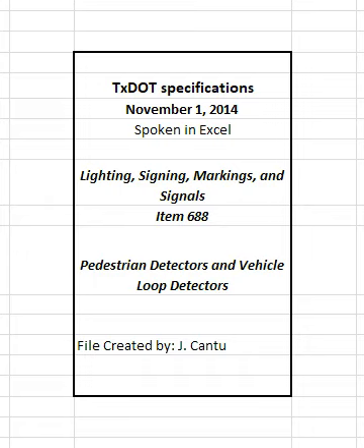2.2 Vehicle Loop Detectors. Use stranded copper number 14 AWG XHHW cross-linked thermosetting polyethylene insulated conductor rated for 600 volts AC for vehicle detector loop wire unless otherwise shown on the plans. Ensure each length of wire shows the name or trademark of the manufacturer, insulation voltage rating, wire gauge, and insulation type at approximate 2 feet intervals on the insulation surface.